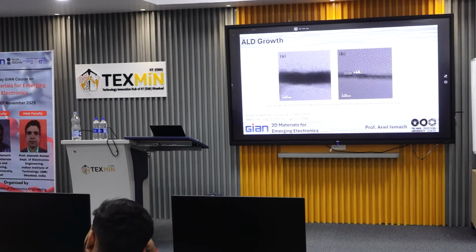When you send one precursor at a time, it's found on the surface. So when you send another precursor, will it go and attach on the top, or will it react with the molecule and sulfur? So you basically are asking if ALD of TMD, for example, is real ALD. How should ALD of the TMD work? First the sulfur layer, then the metal, and then the sulfur. I don't know yet, but I don't think that you can grow like that, right?